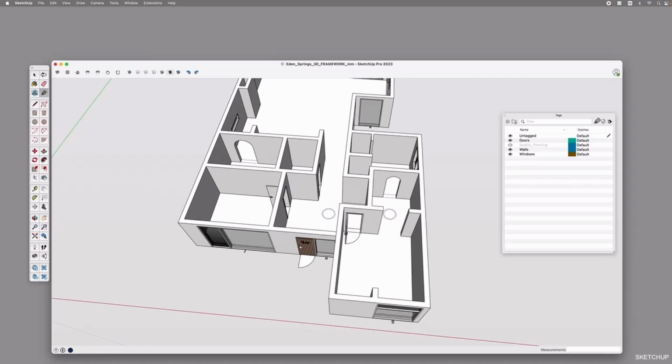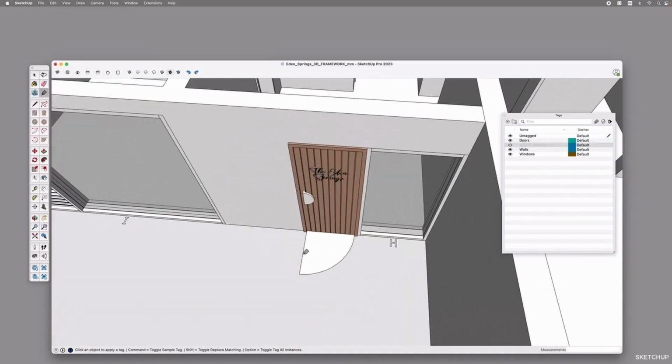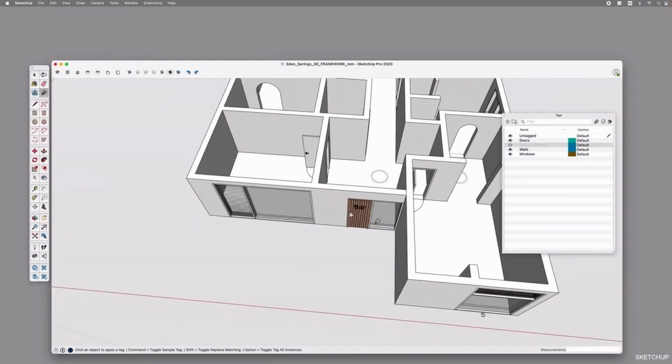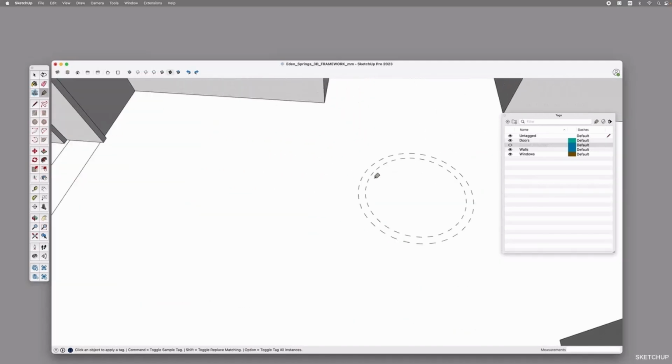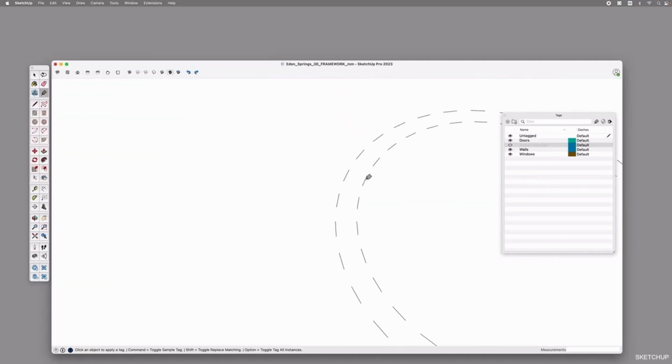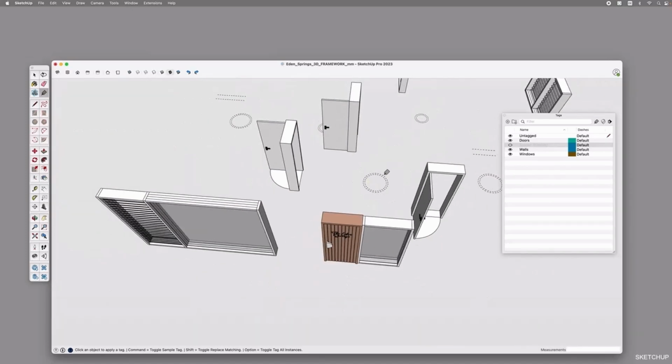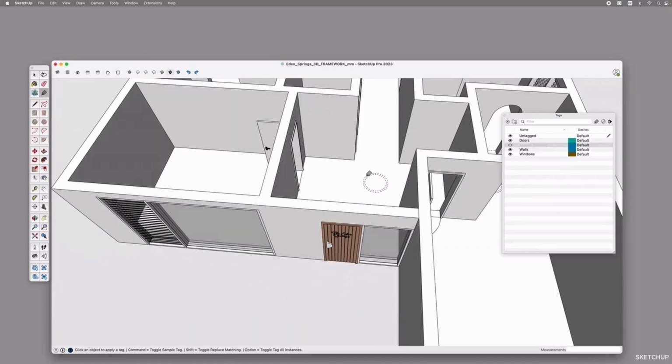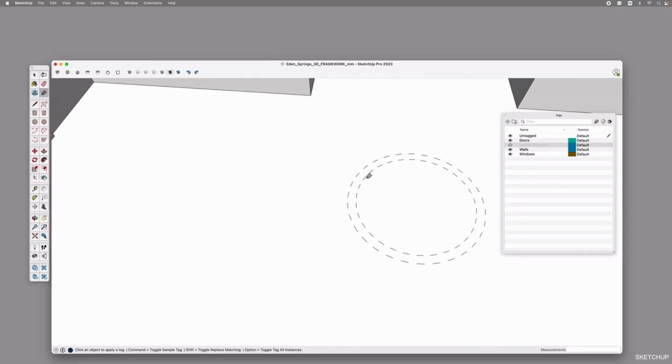First, let's move any 2D symbols that we might still have to the Spatial Planning tag. So I select my tagging tool and click on the correct layer and start carefully tagging those 2D symbols. Just make sure to click on the correct object, as you may start moving objects that you don't want. You can always use Command or Ctrl Z to go back.